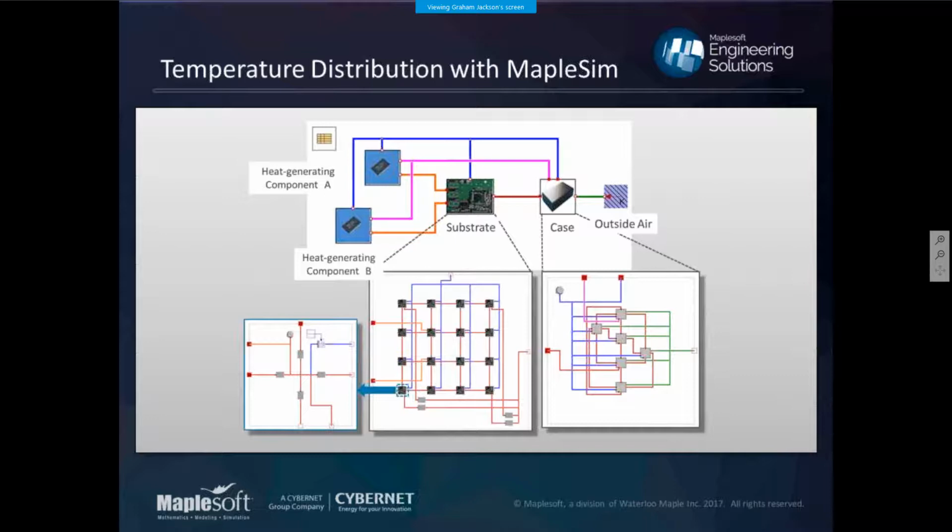So we're adding some levels of fidelity here just to tease out the specifics of what we need. So it's a fairly detailed model compared to just simply the thermal network method shown on the last slide. And in this, it's going to be possible to represent the rough placement of heat generating parts and fixing points between the substrate and the case, depending on where the heat generating parts are connected in that divided substrate. So that's kind of what our setup looks like.